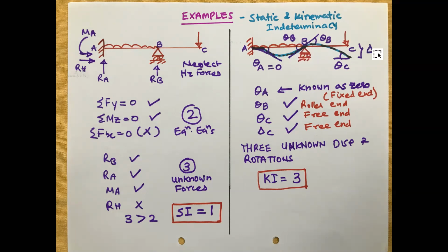Now again, please understand because of uniqueness of displacement or rotation quantity, this theta B and this theta B cannot be different, because of the integrity of the structure, continuity in the structure. Theta B of span AB at end B and BC at B end cannot be different. So I have shown the deflected shape and rotated shape of this beam.